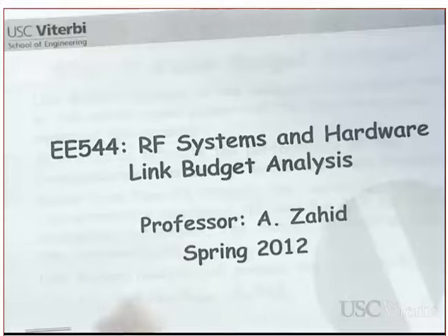This terminology, I need you to understand it. When people ask you, is the link closed? What does it mean? Is there a margin on your link budget? Did you get this or not? By the way, if the link budget margin is 0 dB, we still call the link closed.